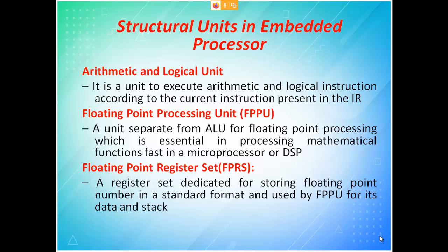Whereas in the 8051 microcontroller, the MUL instruction and DIV instruction are brought in. But you can even do multiplication and division in 8085, where the program lines will be more. You will use repeated addition, whereas they have reduced the number of instructions, that's all. But the ALU doesn't have any block for multiply or divide. The ALU will have blocks only for addition and subtraction.